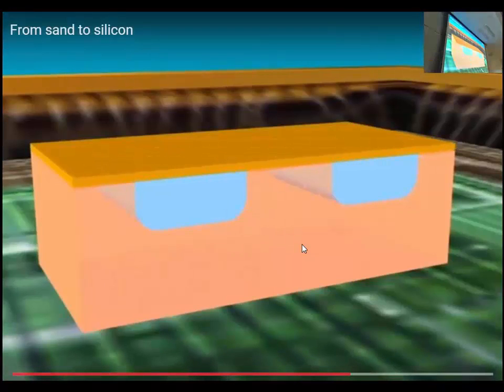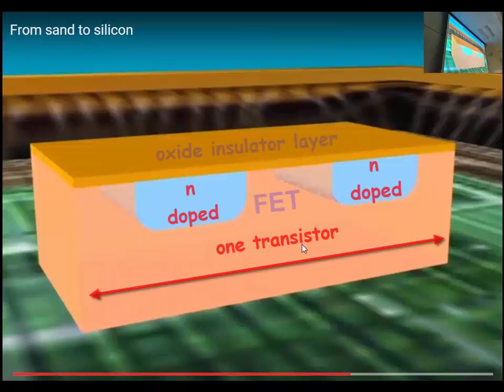An additional layer consists of silicon oxide and acts as an insulator. Okay, so before we make it too confused. Here we took the silicon lattice and they've doped these regions. There are different ways you can do it: diffusion or ion implantation. What they did is they etch with photolithography, expose these regions, then implant. That can be just diffusion, in a high temperature with a little bit of phosphorus or boron.